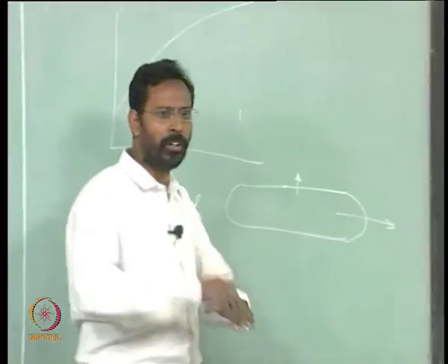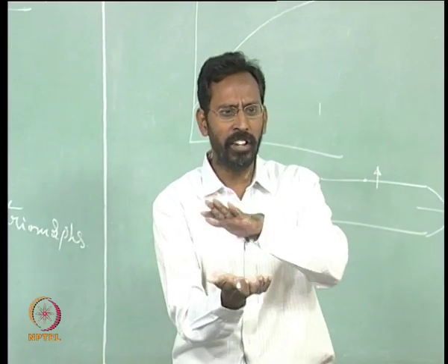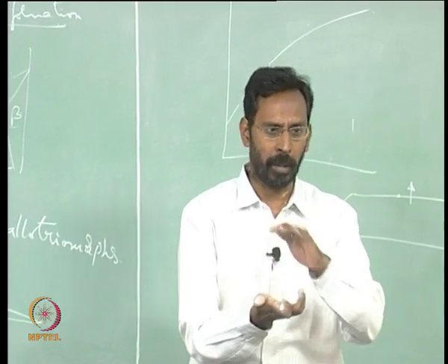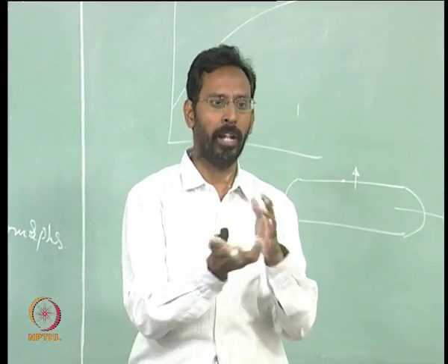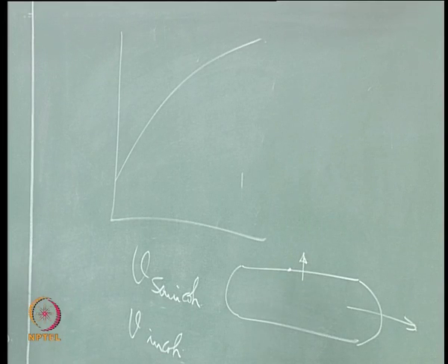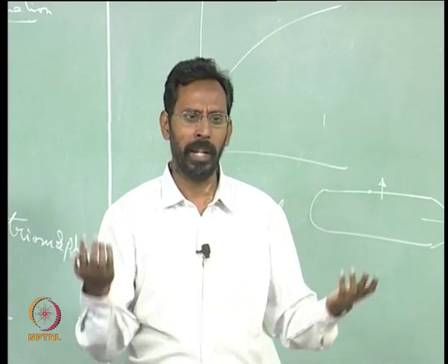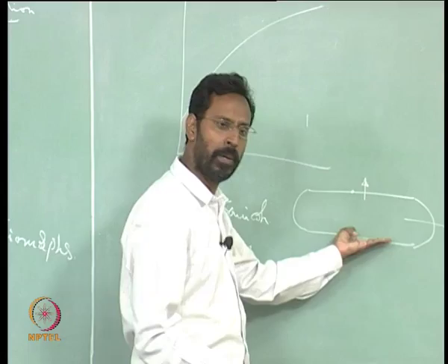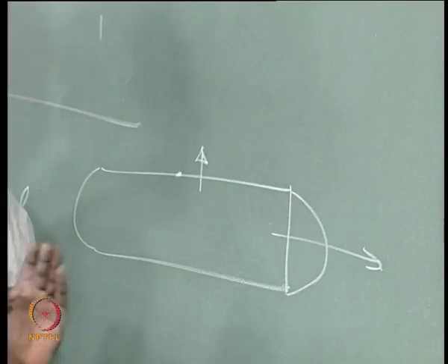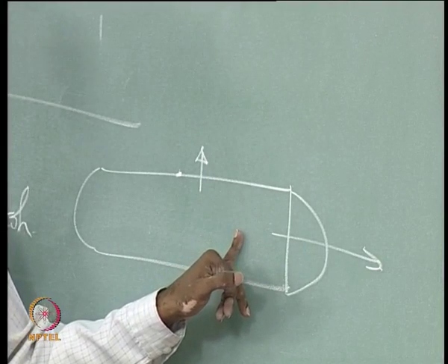because whenever you are talking of coherency, it is on any particular plane. When nucleation is taking place, okay, a plate is nucleating on a matrix, let us say a theta double prime or something like that, nucleating on an aluminum matrix. So the 111 plane of the aluminum matrix acts as a nucleating site. So it is only that plane which is oriented with respect to some plane of the precipitate, whatever plane it is, and once you see that, this is the precipitation, and then if you look at both the sides, if it has to maintain coherency with another plane of this, there may not be a plane which is perpendicular to this which is also coherent with the matrix and the precipitate, you may not see that.